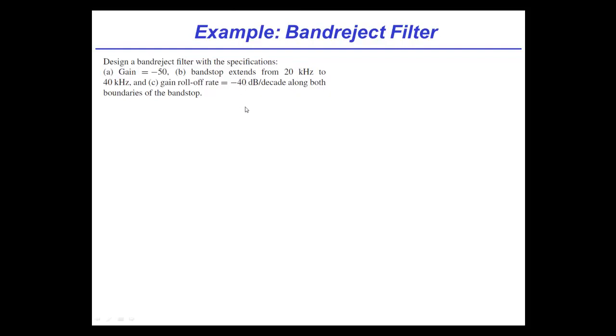Okay, wait, before you put anything on the screen. If I want a second order filter, and I remember band rejects are composed of a low pass branch and a high pass branch, and then you sum them, right? And I want a 40 dB per decade drop, which means that the low pass branch is going to have 2 filters to give me the 40, just as we did in the last slide, and the high pass branch better do the same thing. Right, so you would expect to have 4 filters total.